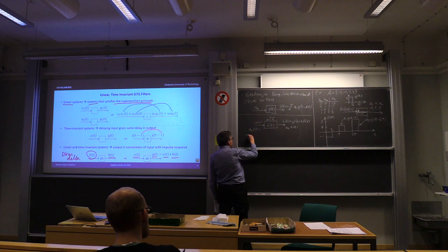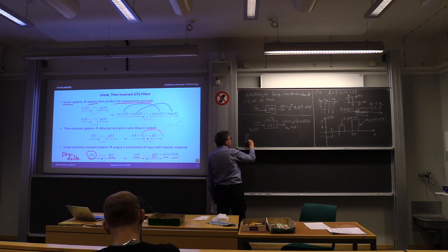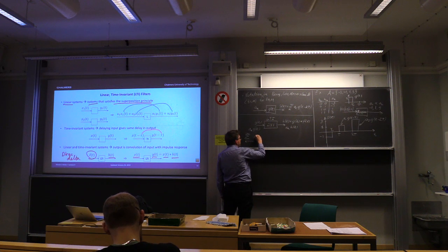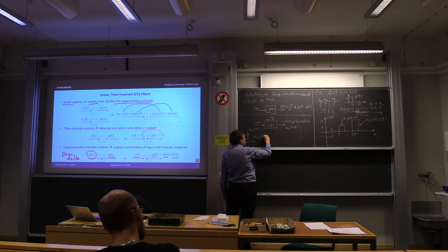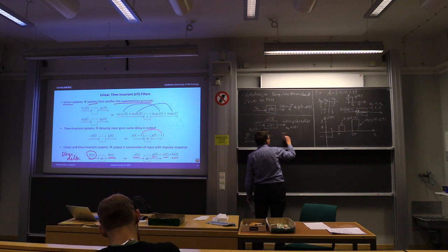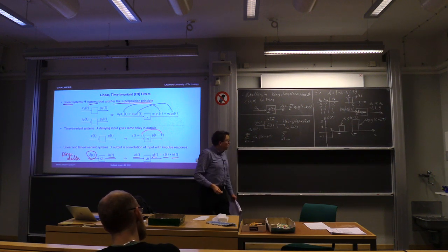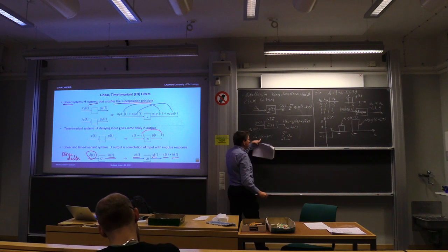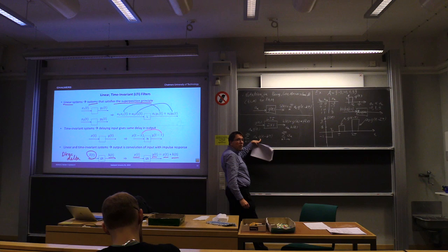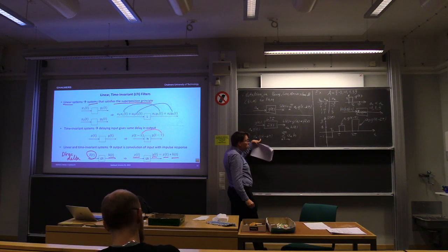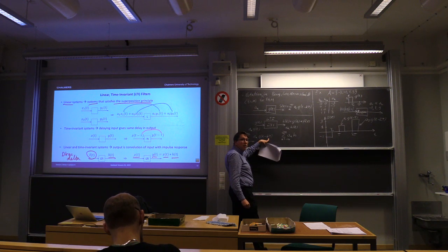Now, if we take the full pulse amplitude modulated input, which is the sum over all k of a_k g(t minus kT), what is the output? Well, it's a sum, due to linearity, with the same amplitudes a_k, and then the response to g(t minus kT), which is h, because g gives h, and then it's delayed by kT seconds.